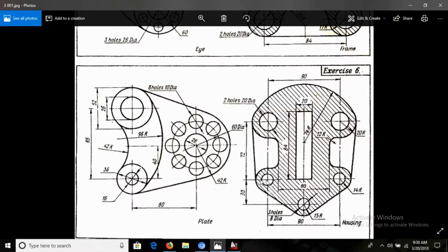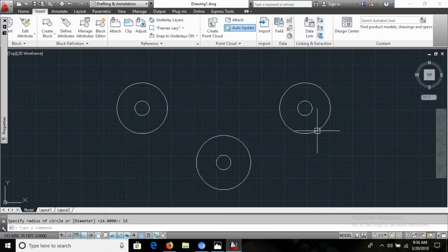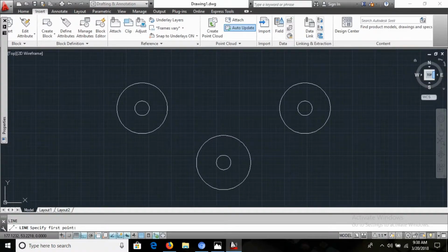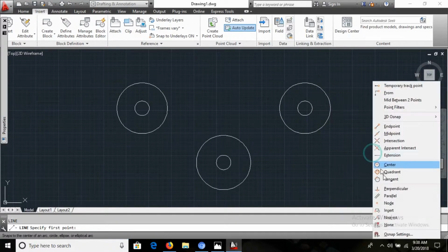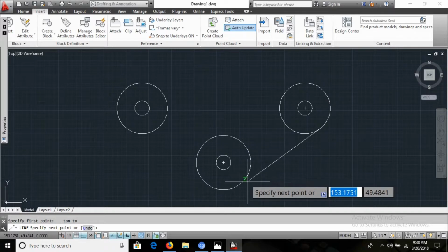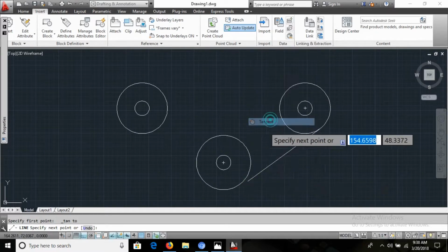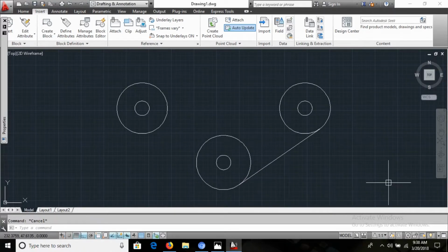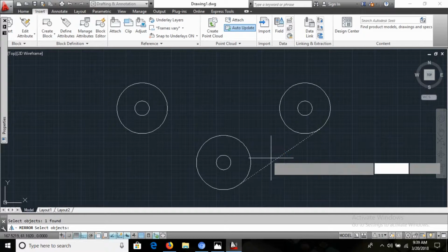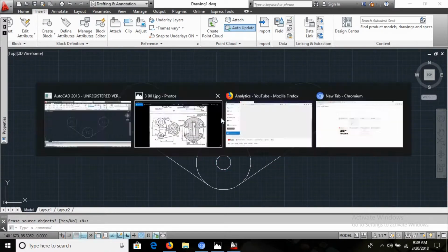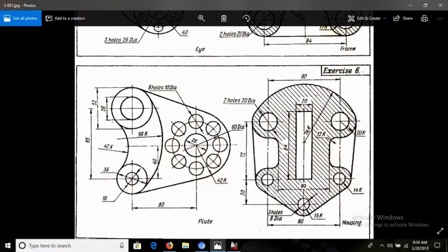Yeah. Now what we need to do is, I want to draw one line here. This line is L enter, and shift right click here, and I go into the tangent, and make a tangent, shift right click here and tangent. Okay. Now I want to do a miter of this. Select this also. And I want to be getting miter like this. Right?